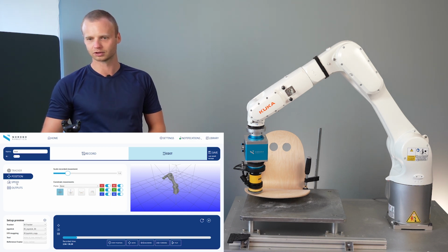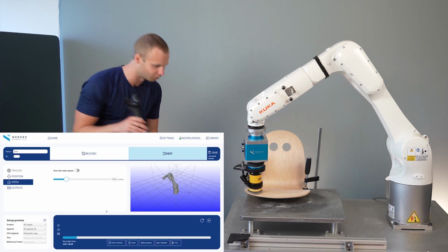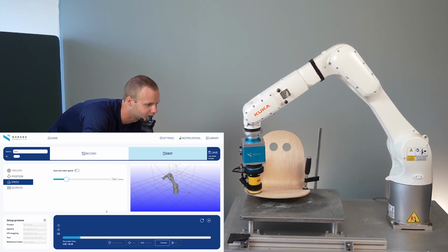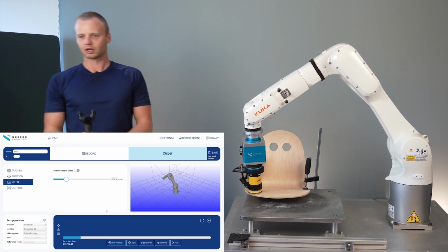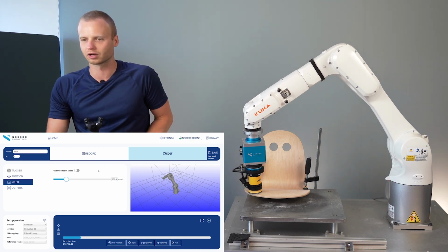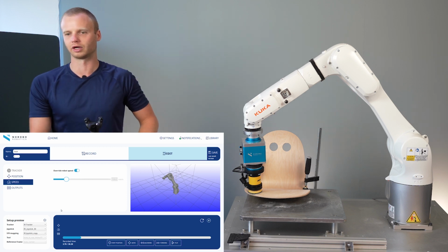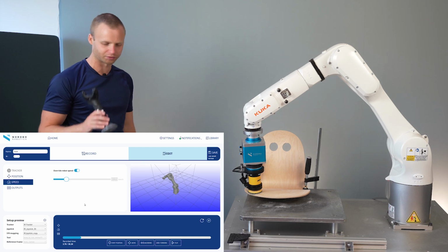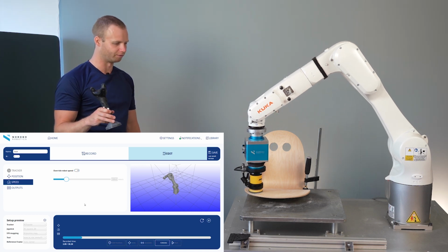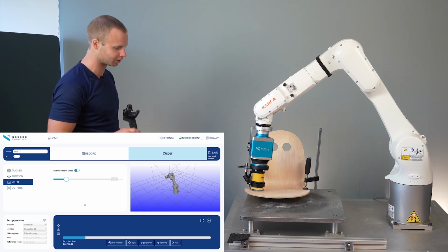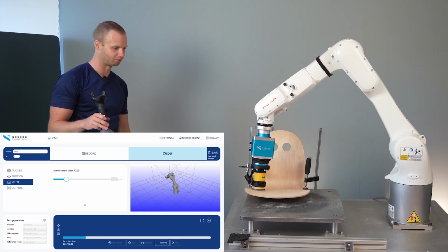So if I go into the speed tab here. I forward the robot until I hit the workpiece. And now I want the robot to go at a constant speed, and I will let it go at 100 millimeters per second. I'll hit override robot speed, and now everything that I forward over will have the constant 100 millimeters per second when we play the robot program later.